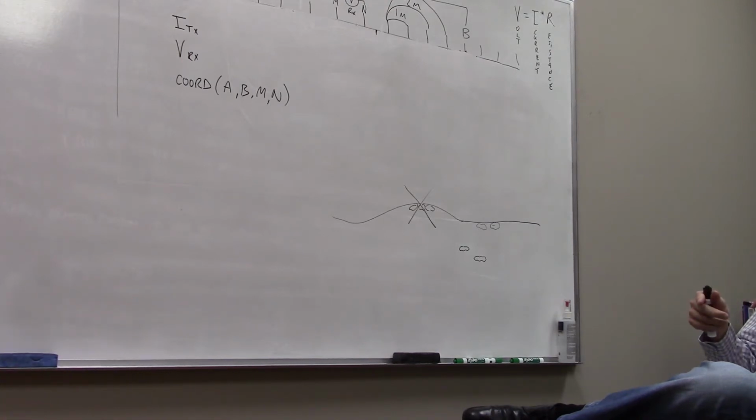The same way as when our clients are looking for old culverts or tanks or pipelines or utilities in the ground, we don't actually detect those typically directly. With a conductor or fiber optic in the ground, we're not going to see it. It's too small, right? So what we see is the trench that they dug. That's really easy to find, because you took the material, removed it, mixed it up and put it back. It's no longer the same as when it was deposited naturally.